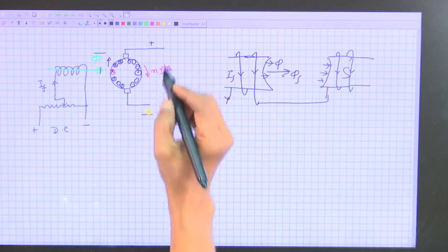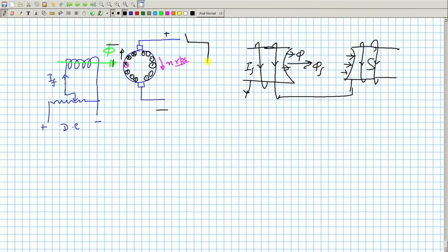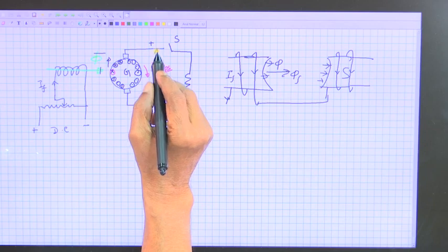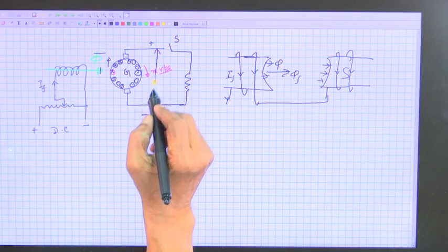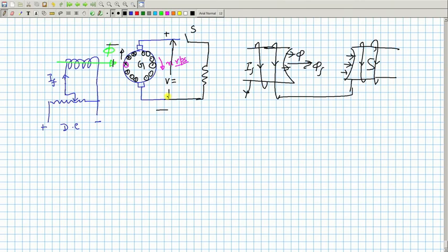And suppose you make an arrangement, you will get DC voltage. So, if it is generator mode, that is what I have assumed, I will connect a resistive load, and the switch is open. With the switch open, this voltage here is the open circuit voltage, given by P z by A phi into N, so much volts you will get.